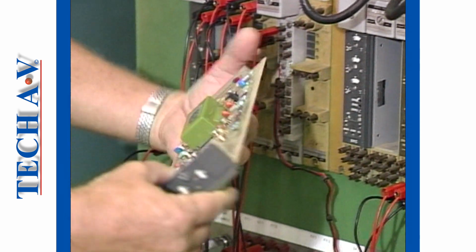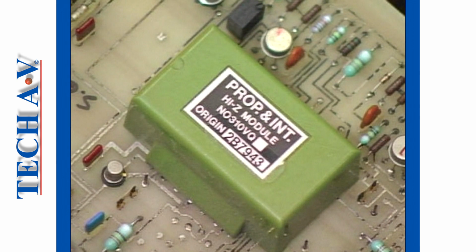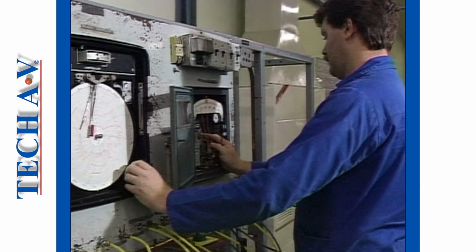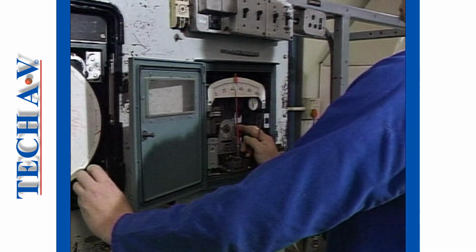Control units, such as in our example, are often created using electronic components to monitor the system and to send the required signals to the final control elements, which is the steam valve in our case. Other controllers may use pneumatic or hydraulic components, but the general principles that govern their behaviors are all similar.